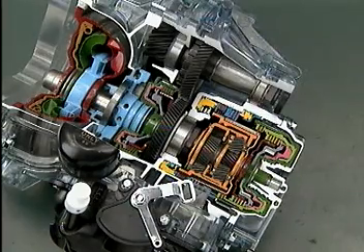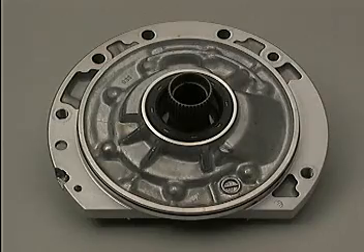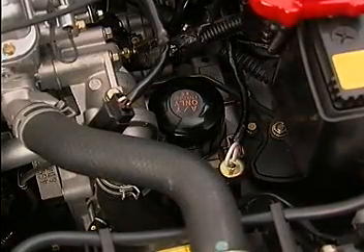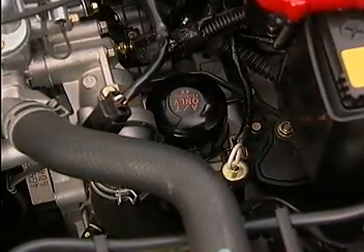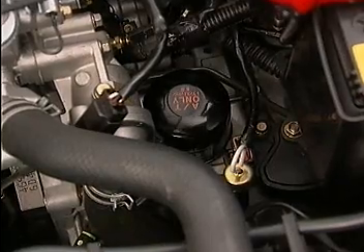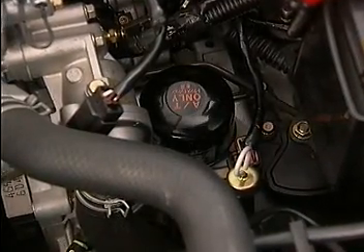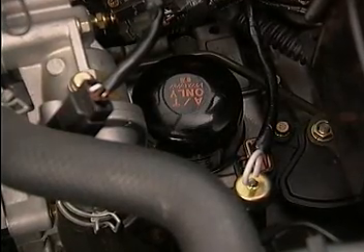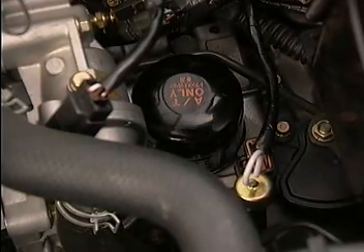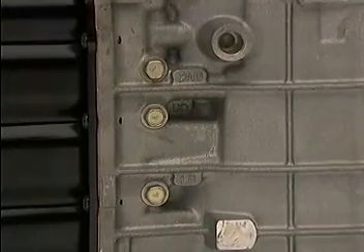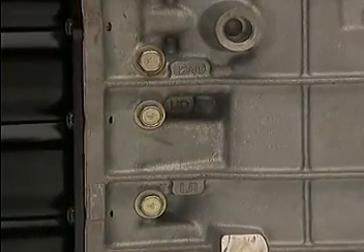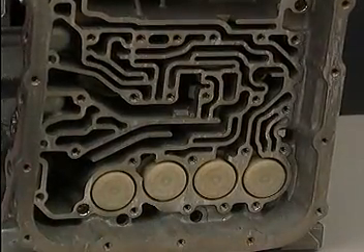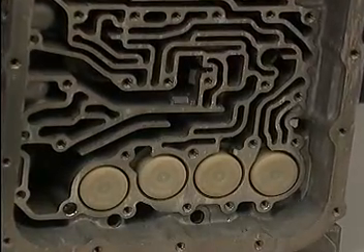less weight. The hydraulic circuit consists of a front oil pump, which is not serviceable and must be replaced as an assembly. Two oil filters, which we saw in Part 1, consist of a spin-on external subfilter. Never install an engine oil filter here. And a main filter, which is not replaceable, except during a complete transaxle overhaul. Pressure ports for servicing, and 4 accumulators which help control the quality of the shifts.